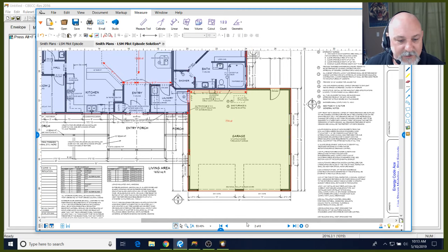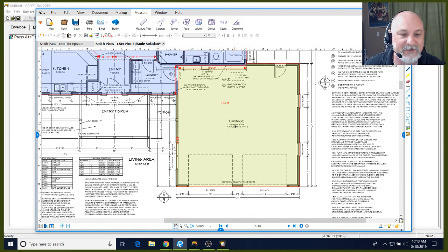So our garage here, technically we've got to have a 6-inch step down in that garage, so it's 9'6" for our garage. So we have 28 feet on our front wall, 9.5 feet gives us 266 square feet. For our left wall, we've got 21 lineal feet, 9.5 times 21 gives us 199.5. I want to round that to 200. You could input the decimal. That's all cool.